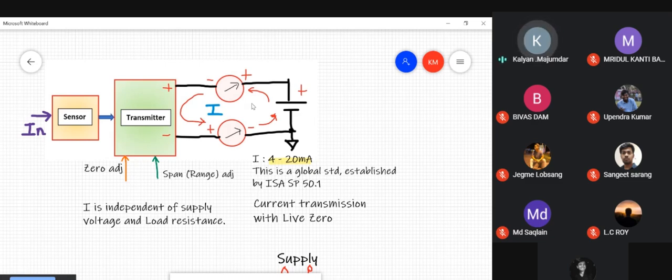Now, in addition to the power supply, of course, if you are using a transmitter, then you have to use the signal somewhere. If you're not using the signal for any purpose, then why do you have a transmitter? The simplest of devices is an indicator. Of course, I've shown 2 indicators. Not that you have 2 indicators. You can have 2 indicators, nothing wrong with that. But the indicator can be located either on the upper line or it could be located on the lower line. Both are equally permissible, both are equally acceptable. So it forms a closed circuit, which is called a loop.